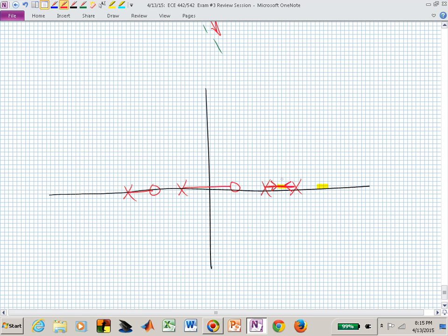And these now are going to maybe do this, depending on where you would calculate the centroid. You know the asymptotes are at plus and minus 90. This guy's going there, this guy's going there. Is that clear? And depending on where the unit circle is relative to those, depends on whether you have a stable system or not.